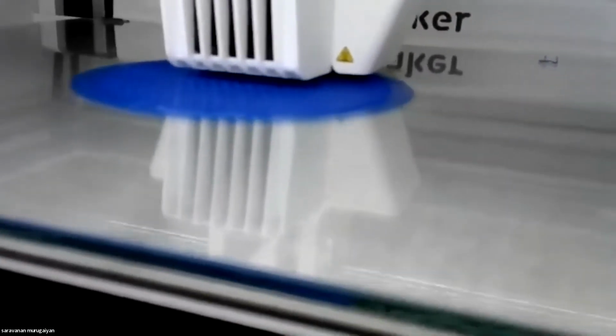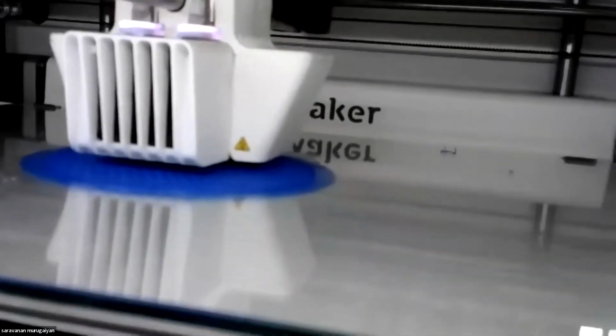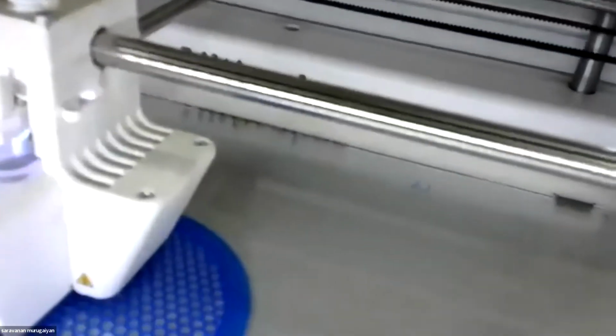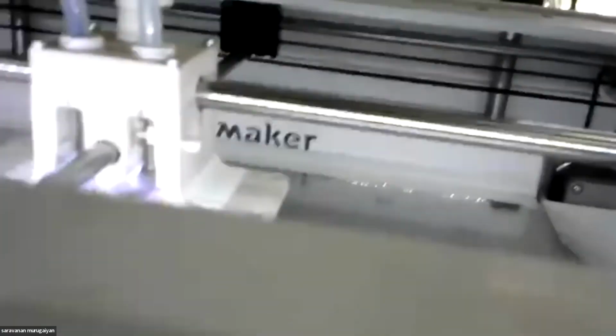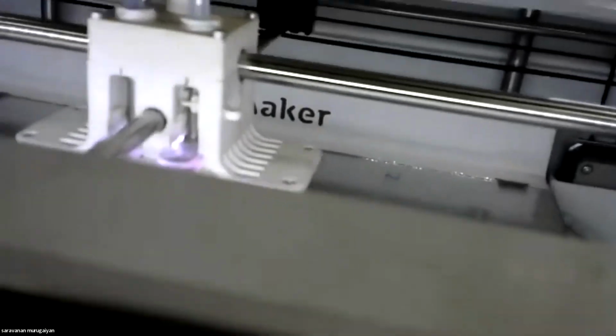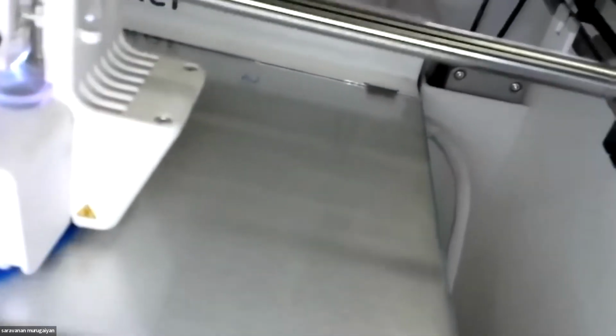Coming to the different capabilities of the printer, it can also print 2 different materials simultaneously. And when the material extruded is of uniform or definite pattern, the printer takes a specified infill pattern. That is, when we are giving the component, if the component is not to be completely fully filled, it is defined by a specified infill pattern. The infill pattern can only be given when the material has a specific thickness.